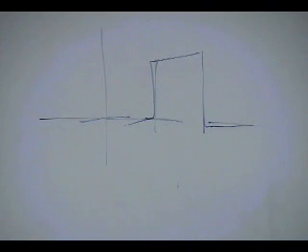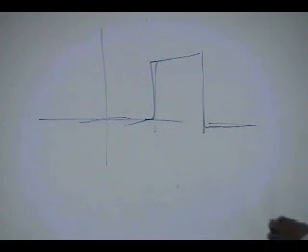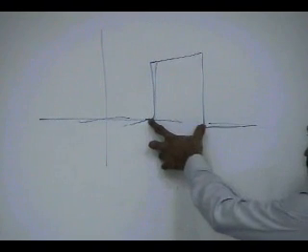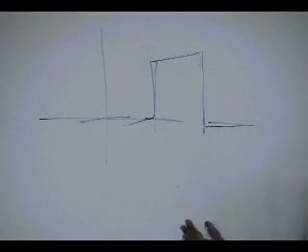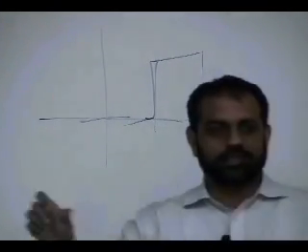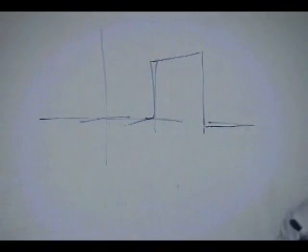The problem is that many a time the noise is random. You don't know. The channel is random. It is just changing all the time. And it is in-band noise. It is getting into your spectrum. So designing something like this will not help you because noise does not exist in a separate spectrum. It is part of your signal. So you have to combat the noise.